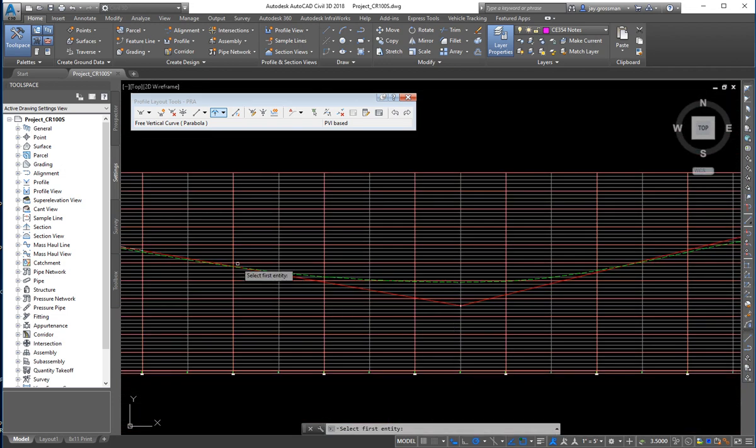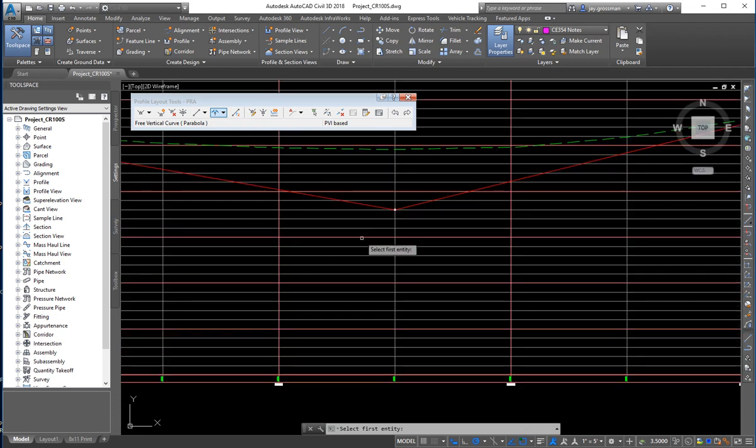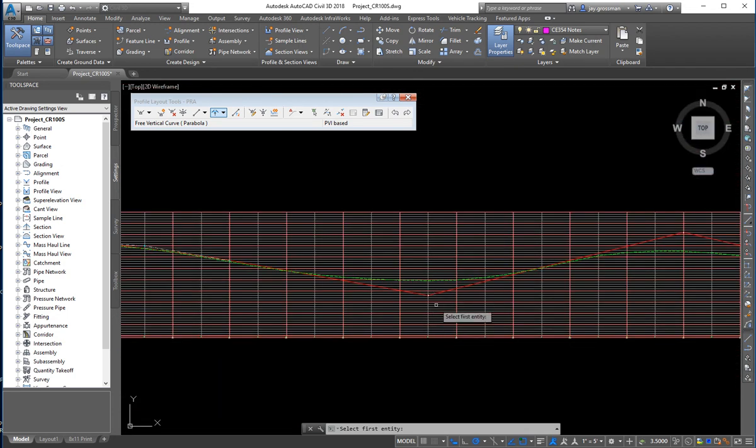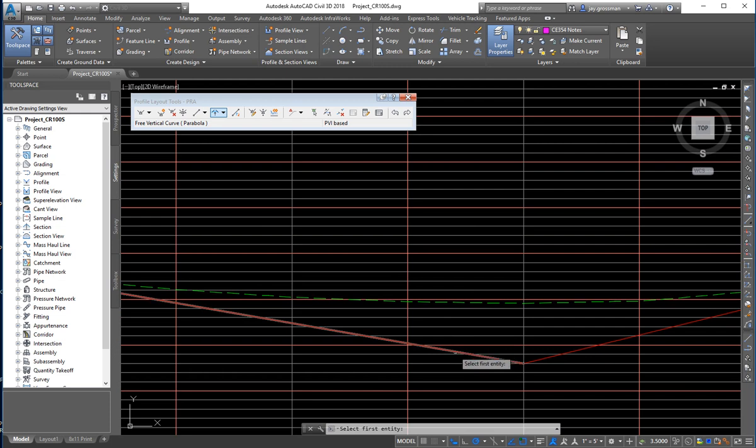Now this one, we're also going to put a really huge curve in through there. I guess this is 100 feet between the darker red lines. So we're going to aim for 100, almost 200 feet each side, so about a 400-foot curve. So let's try that. I'm going to hit that. Next entity there. Let's try this one at 400.